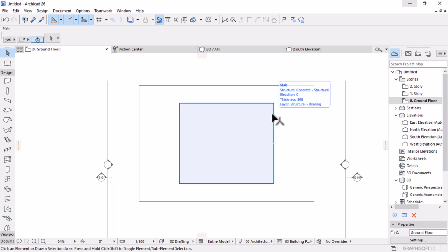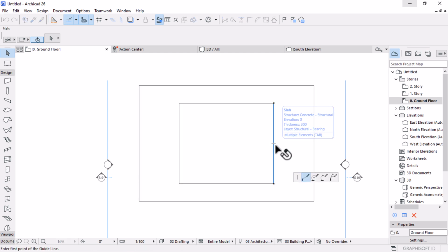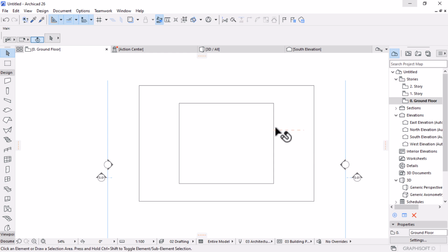Okay, right. So once we're done with this, let's move on to the next step, which is the actual classroom or the actual building itself. So what you need to do is I'm going to press Alt L to add a guide. It's a shortcut to adding a guide. And then I'm going to draw a guide from this side to the other side by 4.3, 4,400. Okay, and then I'll do the same, Alt L, and then draw another guide this side by 4,200.